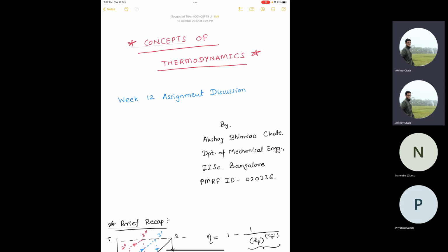You have doubt in the 10th part, right? The ninth is fine, no? Yes, the ninth is fine. So if the ninth is fine, then the system has lost 518.55 kilojoule of heat to the surrounding, correct? So when you do the entropy balance, what they are doing is first m(S2 minus S1), I assume it is for ammonia, is it not? Yes. So ammonia, you found its entropy decrease. Then you found it for steel. Then you subtract, the minus minus will become plus. Then you are adding entropy generation in the universe.